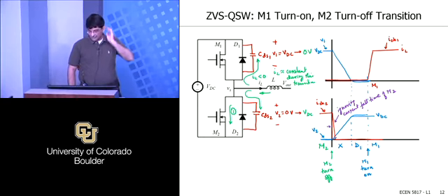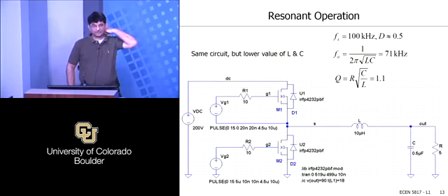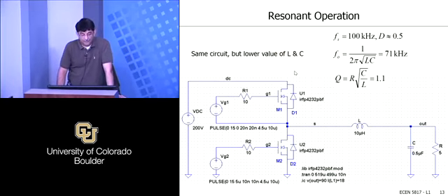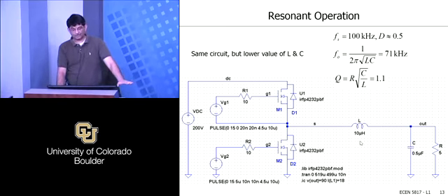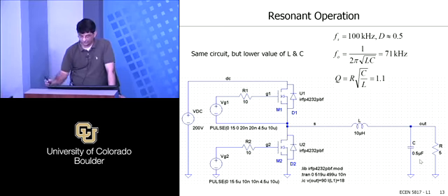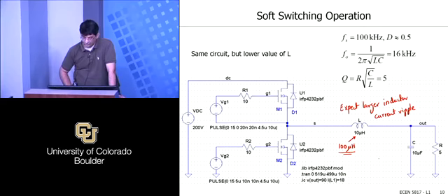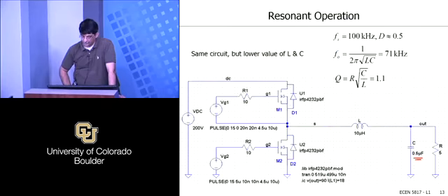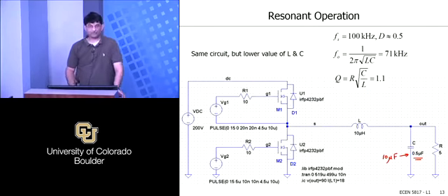Okay, let's then make one more change, and I'm going to go a little faster. So last time what we did was we simply reduced the inductor value. Now I'm going to use the lower inductor value but also change the capacitor value. So the capacitor value is now also reduced. The capacitor value previously was, I think, 10 micro. So I've gone from 10 microfarad to 0.5 microfarad.